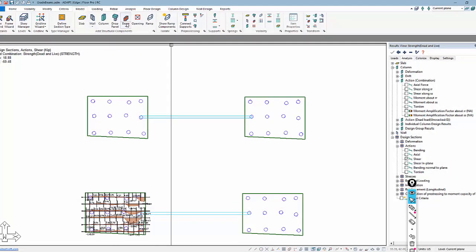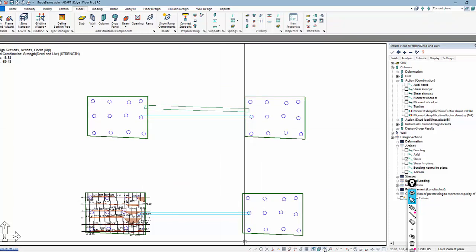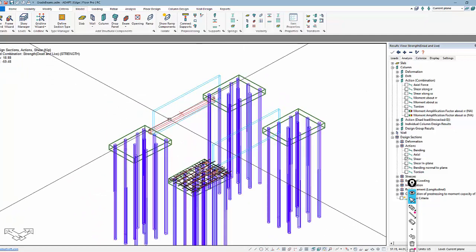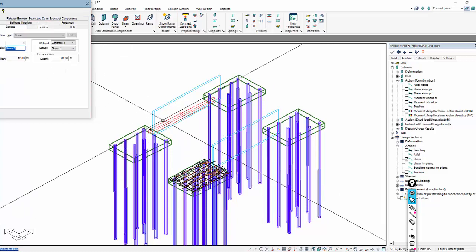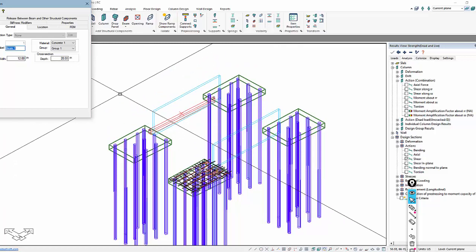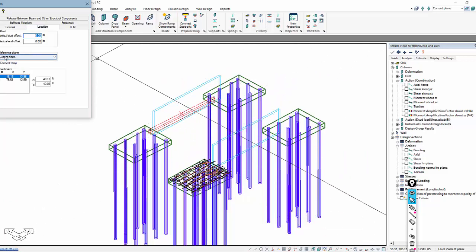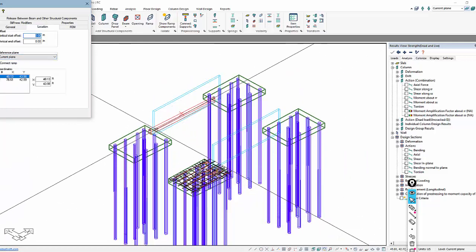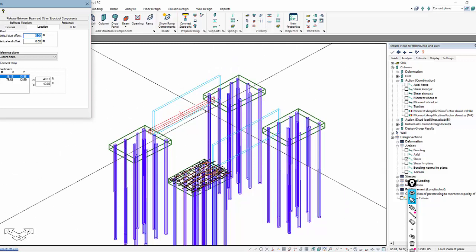okay, we'll go to model. Let's just put a beam along the side of this. If I model a beam along this path, you can see that beam can be shifted vertically. I can create an offset for the beam, so I could create a depth of the beam that's quite tall. It's 120 inches in this case, and then I could create an offset, but that beam still is only connected to one level. There's only one level that's referenced from, so it cannot connect between two levels in order to transfer load through the beam to the level below, and that is problematic in trying to set up a model like this.